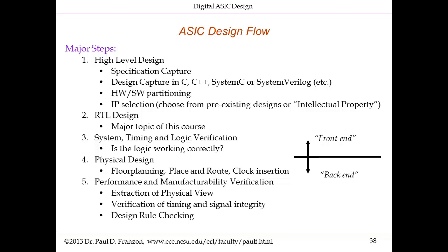And then there's a lot of time spent on performance and manufacturability verification. That is, does the timing work, including the actual delays of the wires? Signal integrity refers to whether the noise levels are too high, for example, due to crosstalk. Power integrity: you're worried about the impact of large current draws on your ability to deliver that in the power network. Design rule checking and electrical rule checking refer to whether the details of the layout are such that the end product will have a high yield.